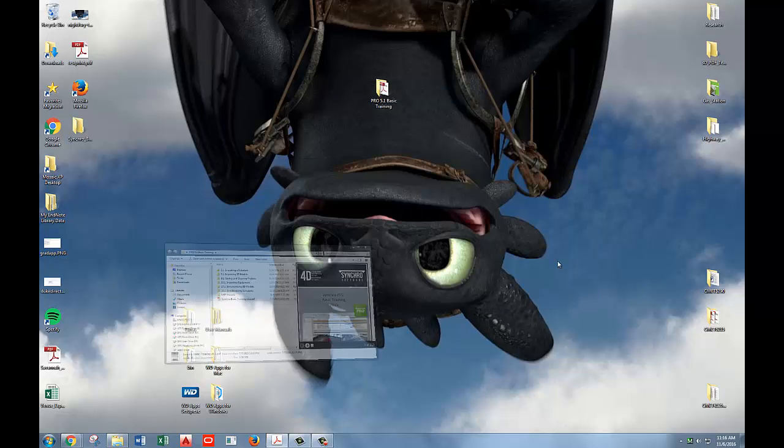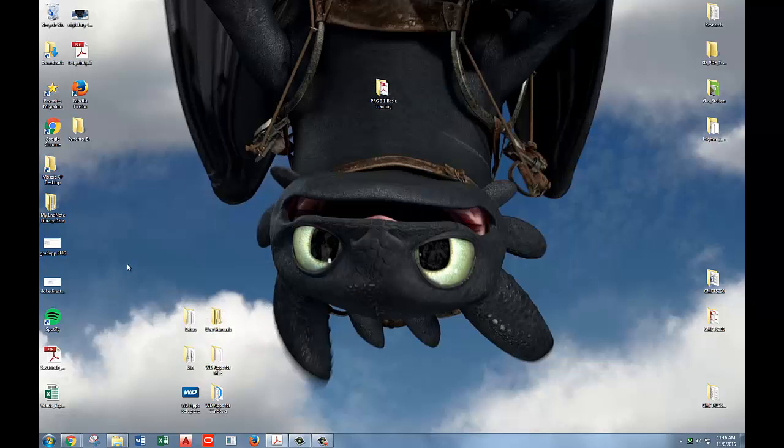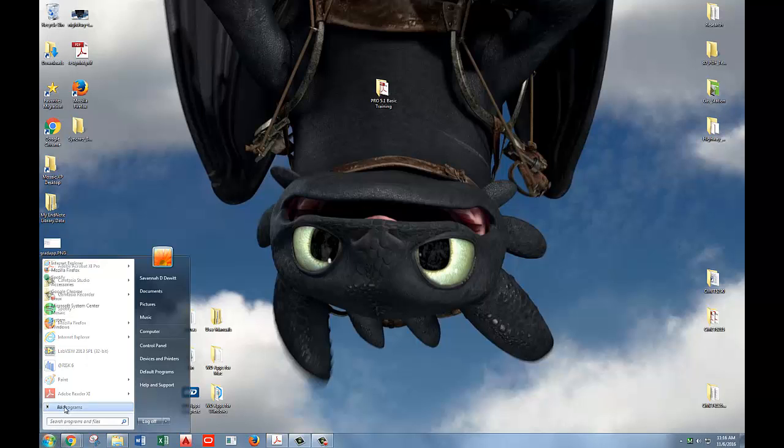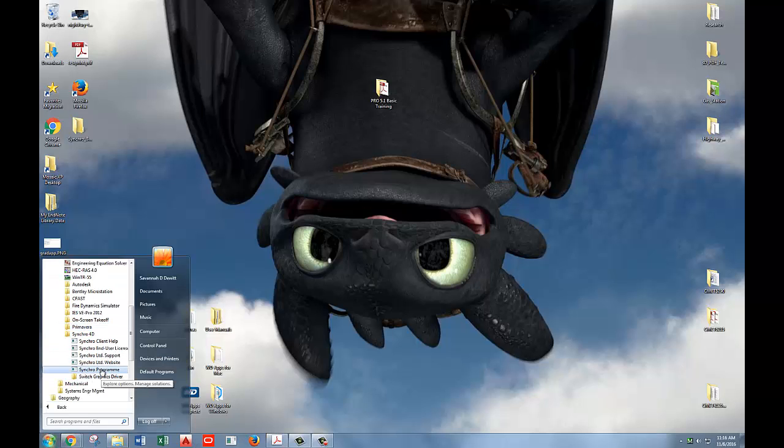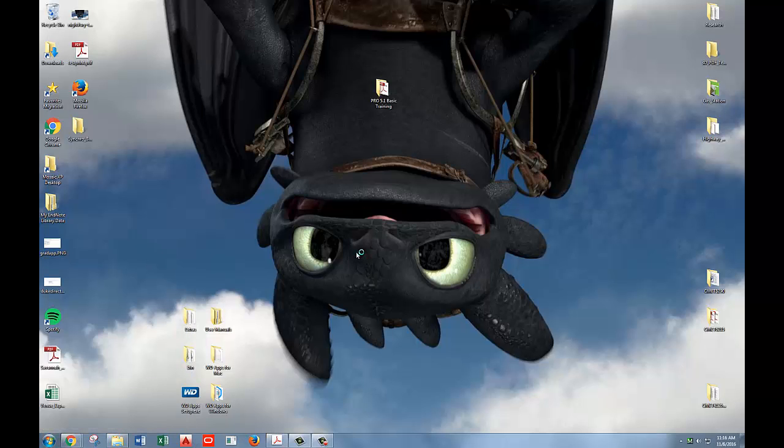So let's go ahead and open up Synchro. Just go to Start, All Programs, Mosaic, Engineering Tech, to Synchro 4D, and pick Synchro Program. Click on that and let it load up.